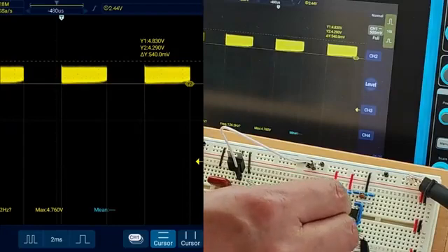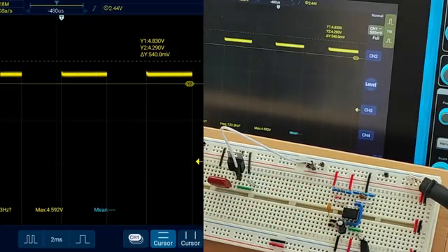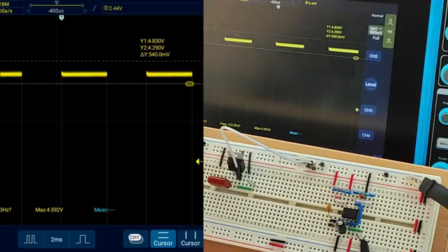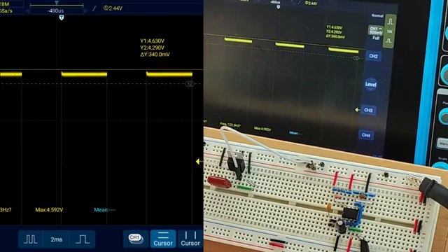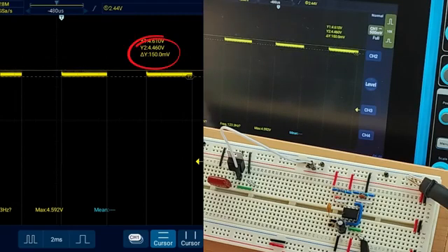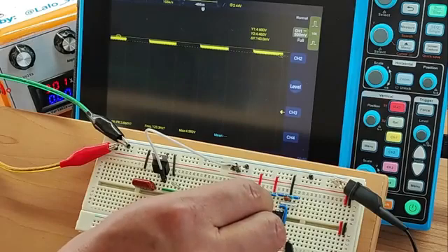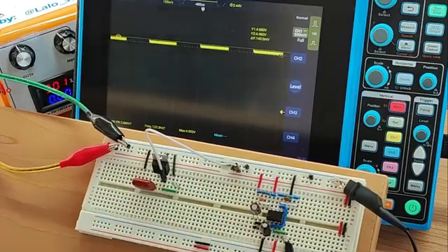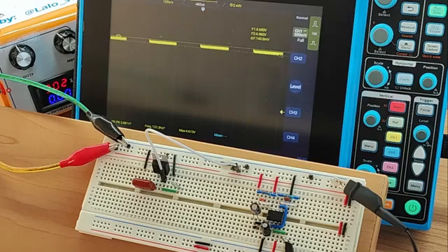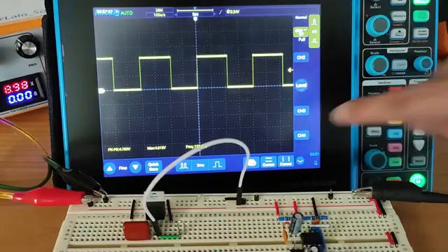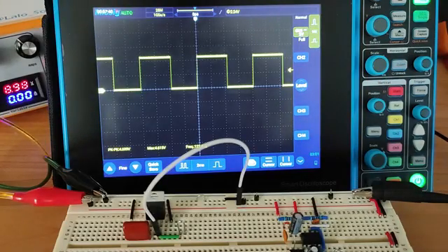Now adding the first of the two decoupling capacitors of the 555 timer. First, with 0.1 microfarads, or 104 code for a ceramic capacitor, which should remove higher frequencies. This gives like 140 millivolts for the noise. Now, adding the electrolytic capacitor of 1 microfarad. This one should remove the lower frequencies from the noise. This one is only helping to fix the left side of the shape, but not for reducing the overall noise. Anyway, we'll leave it as it is prescribed by the datasheet.